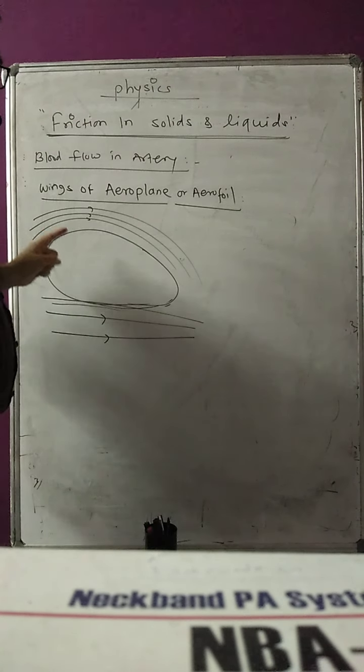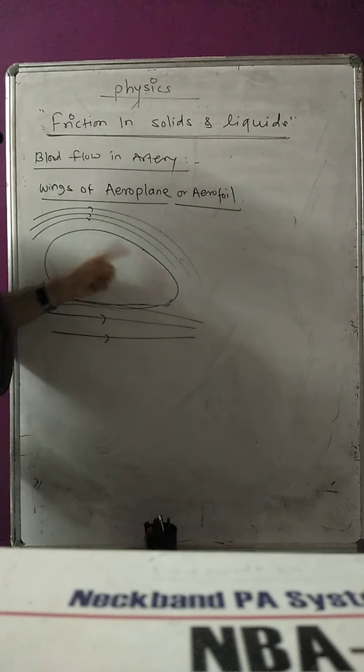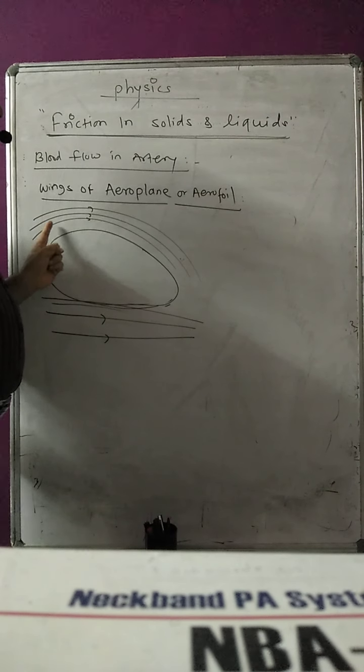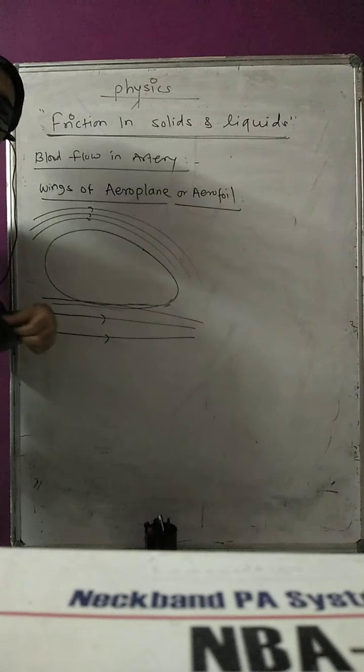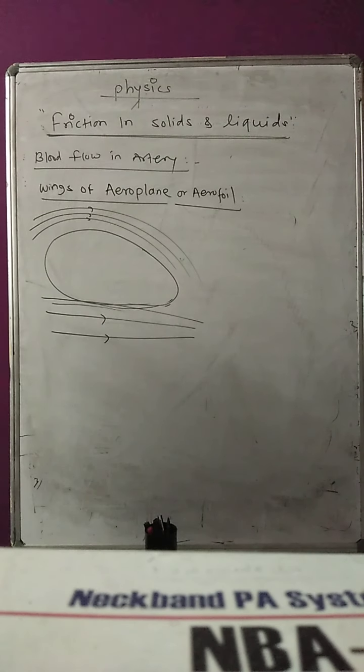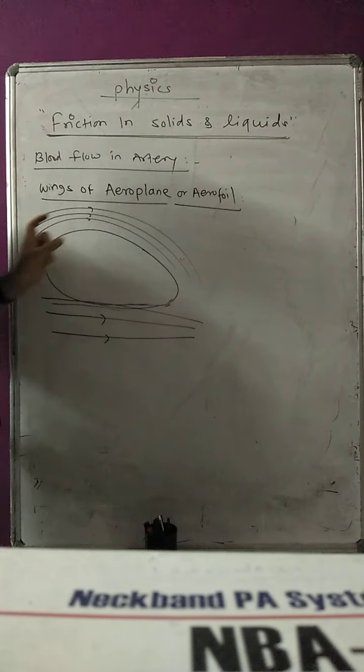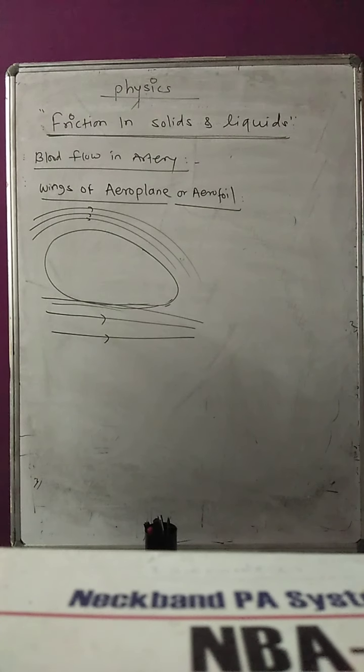Very simple: as this part is convex, the air is going to flow above the convex part. The streamline airflow that passes the airfoil splits at the leading edge but joins again at the trailing edge. Leading and trailing edge. Then what is going to happen? The streamline air above the convex shape gets crowded.